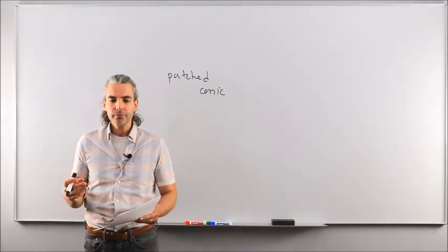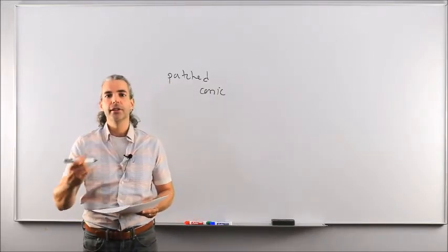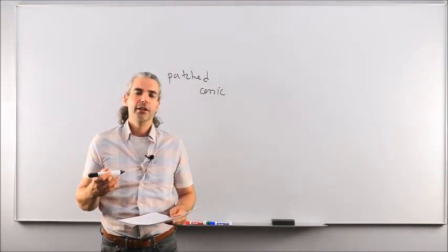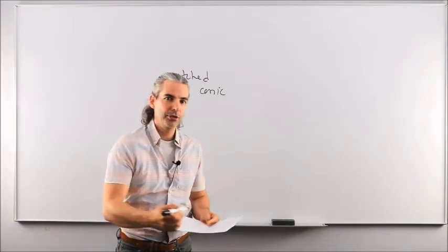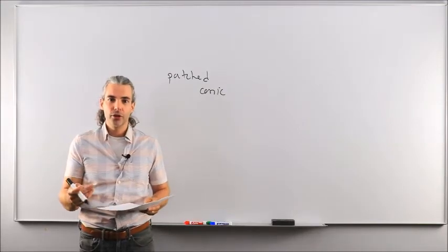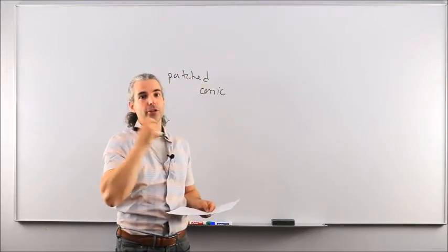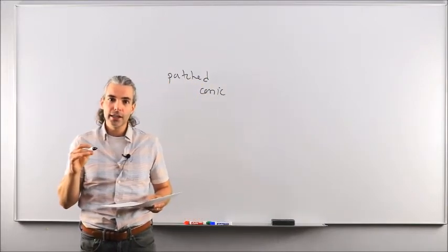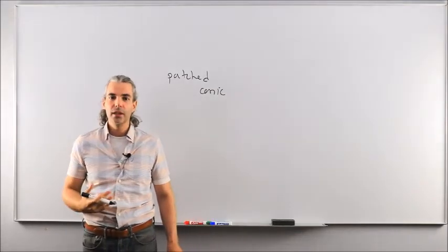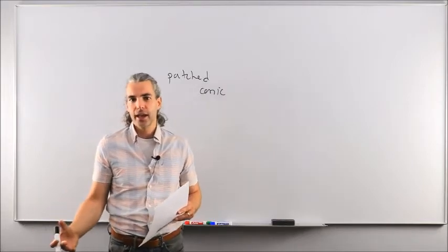Then we'll apply a delta V maneuver that will transfer it from what's known as a parking orbit around the Earth onto a hyperbolic transfer trajectory that will then lead the spacecraft to exit the sphere of influence of the Earth in terms of gravitational attraction. And then the spacecraft will keep coasting for a long period of time under the gravitational influence of the Sun only. And then whenever the spacecraft gets closer to the target planet, Mars in this example, it's going to be pulled by Mars' gravitational attraction and forget about the Sun from that point on, okay?